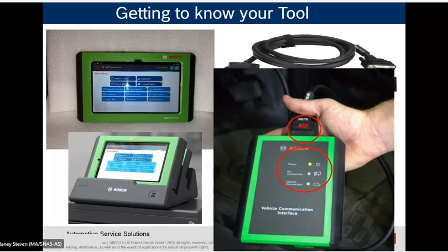So you can do a couple things. You can try to figure out why there's no power there, or if you're in a hurry, you can take the power cord that comes with the scan tool that plugs into that docking station and plug that into the VCI.